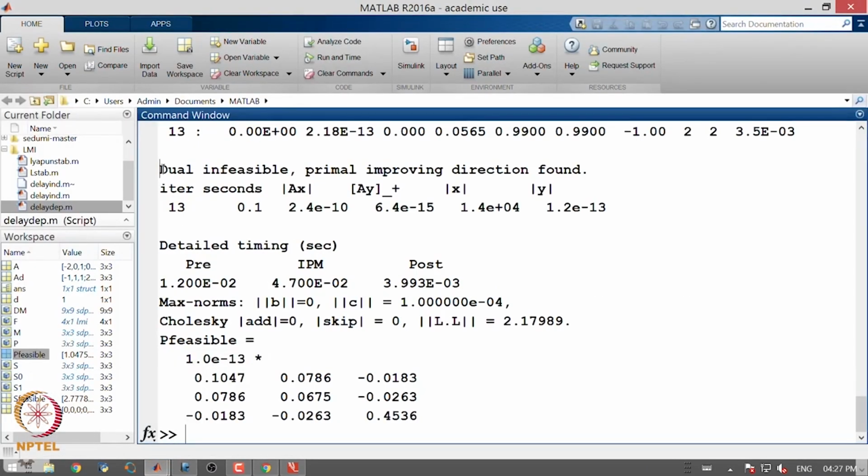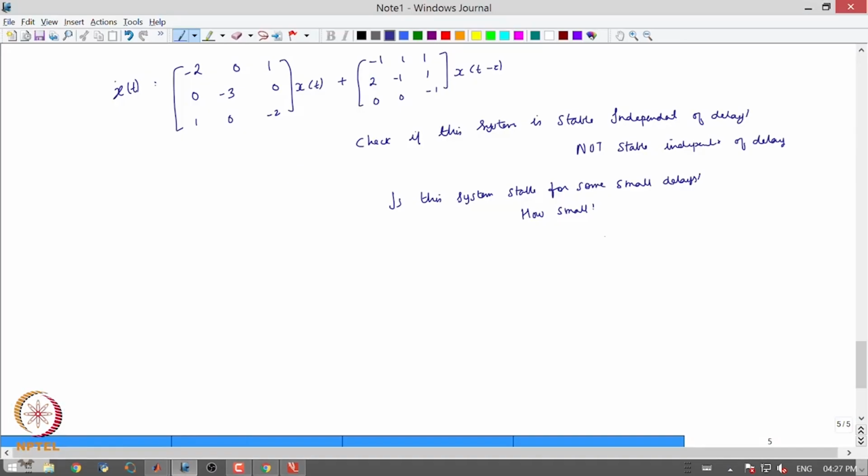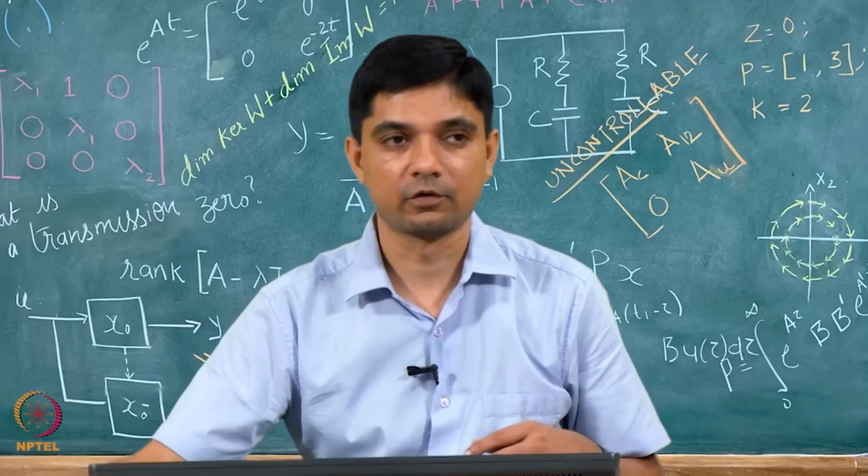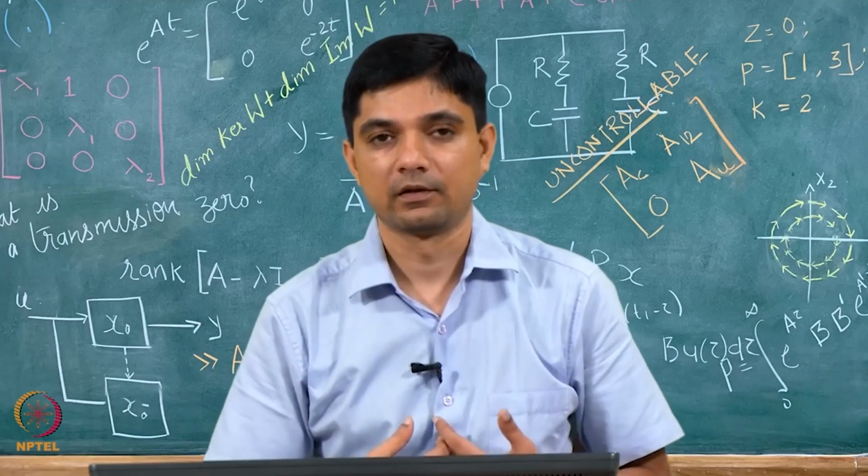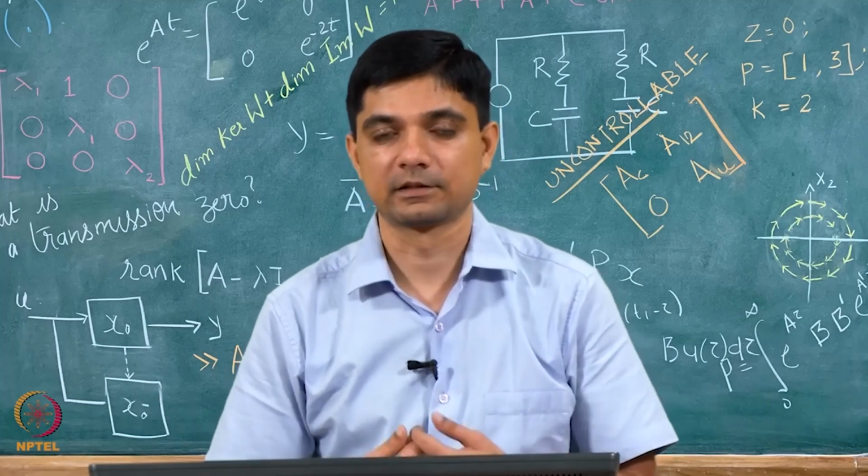Oh no, some infeasibility condition, right. So, two things that I found out: for point 1 it is stable, point 3 is stable, and for tau equal to 1, the system turned unstable. Okay, and then maybe you can just write a little loop to check what is the maximum value of tau or D for which the system is stable.